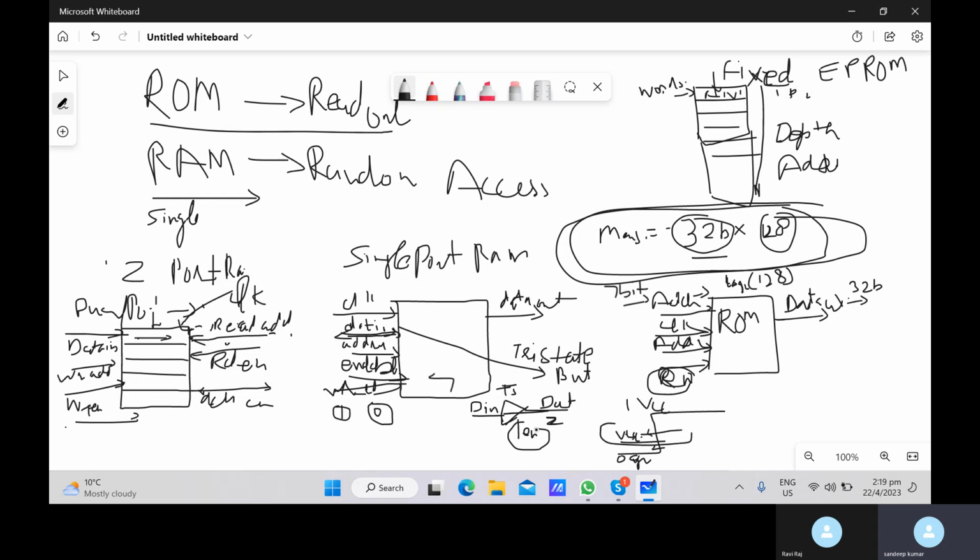So the logic will drive this middle voltage, so that the outside value can drive anything. If it drives zero, it will pull down, and whatever is driven will appear on the bus. Similarly, when the read is there, the outside logic will drive Z. Whoever wants to drive the data, the other should know, so that the other can put its logic into a high impedance state.